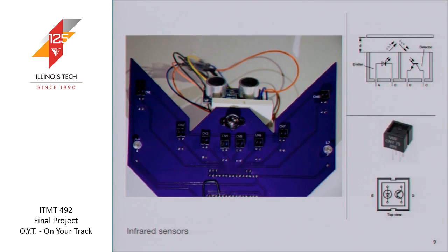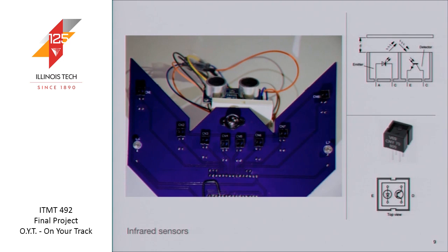As the key point of our project is to follow the line, I will explain a little bit more about how the infrared sensors recognize a line. So these black cubes, as you can see in the picture, basically are an infrared LED and a phototransistor. The phototransistor senses the light that is reflected by the surface. And different surfaces reflect different amounts of light. So the Arduino senses this different intensity of light, and then we can differentiate colors and different surfaces. As you can see, black and white is our path. We are using just 2 colors because this is a small and simple example of how our robot works. But we can also use different colors to develop a more complex system.